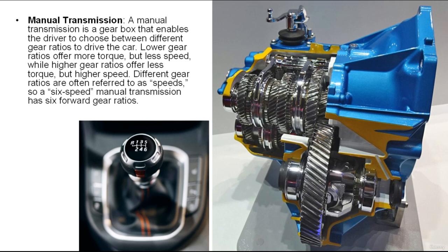If any of the gears in the set are a different size than the others, the gears will move at different speeds. The size ratio of the gear set is called the gear ratio of that gear set. A manual transmission houses a number of individual gear sets, which produce different gear ratios. The driver selects the desired operating gear or gear ratio. A typical manual transmission has 4 or 5 forward gear ratios, neutral, and reverse.